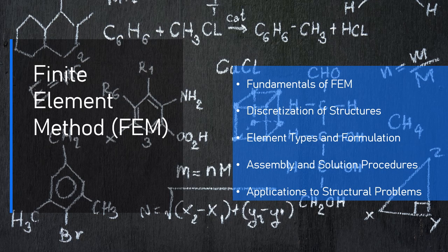Application example: high-rise building frame optimization to reduce material usage while ensuring that the frame meets the required safety standards under seismic or wind loads. Benefits: parametric optimization allows for design adjustments based on different load scenarios or constraints, e.g., weight reduction, cost reduction. Can accommodate complex geometries and irregular load distributions.